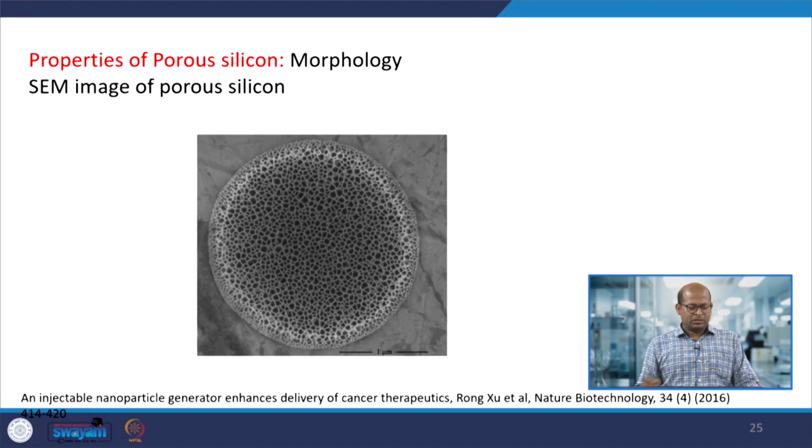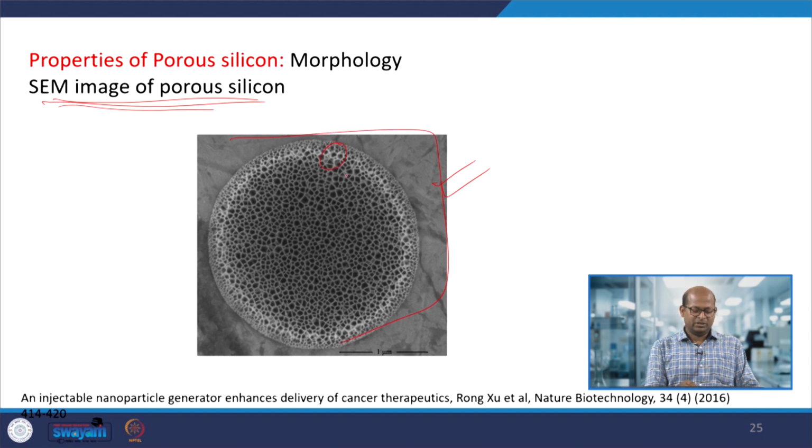Okay. This is the AFM image of porous silicon. You can see the morphology. Once the pores are made inside the silicon, the image is taken, and you can see different types of pore formation. Once we analyze the pore diameters, we can see whether they are micropores, mesopores or macropores, which we can also check using particular characterizations. Okay, so thank you. Today is up to this.